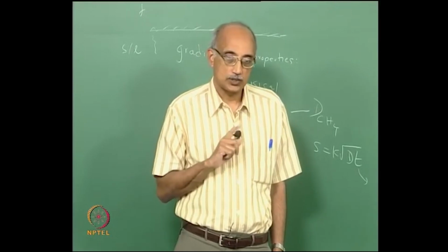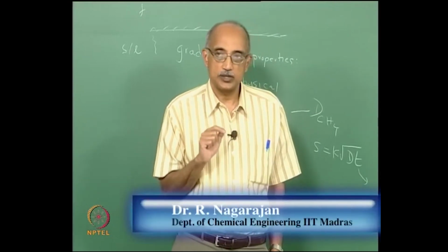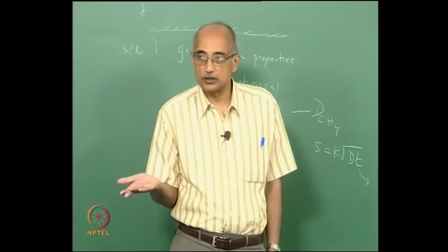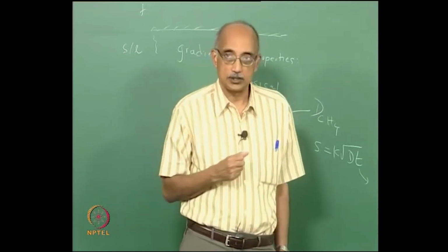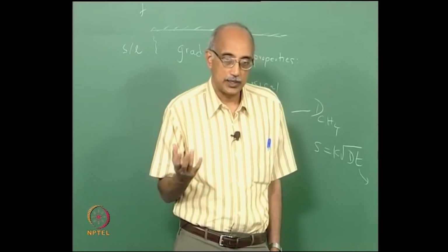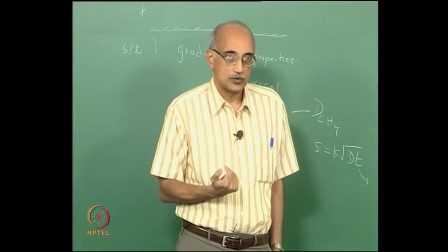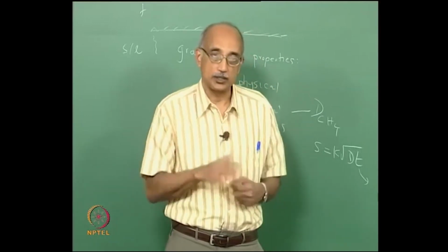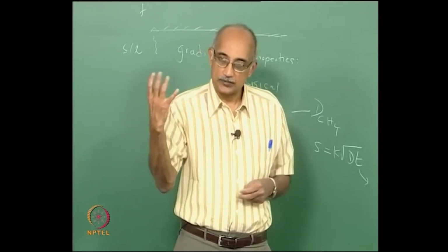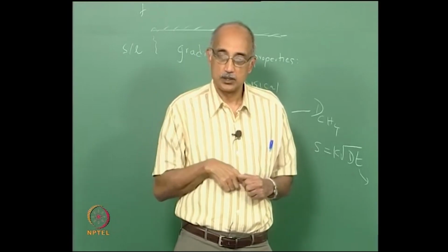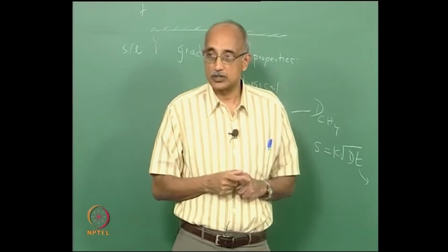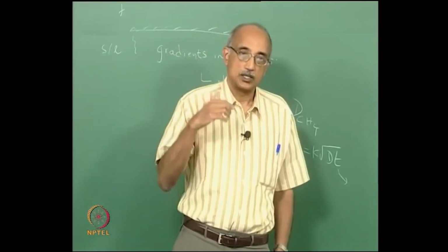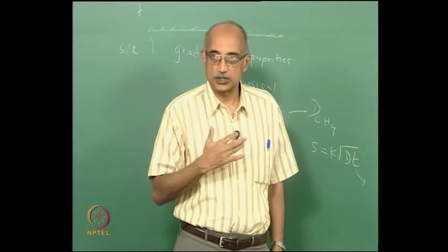But the question you have to ask yourself is, do I need it? Is that really going to give me useful information, or am I better off simply doing, say, an optical inspection of the particle to verify that the outer surface is in control, or maybe I should do something like a porosity test to make sure that the porosity of the material has not changed, its compactability, which is more a function of particularly the subsurface. Flowability is another parameter that you may be interested in. In that case, again, what you most care about is the outer surface and the subsurface regions.